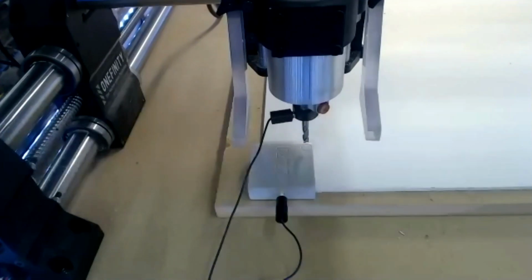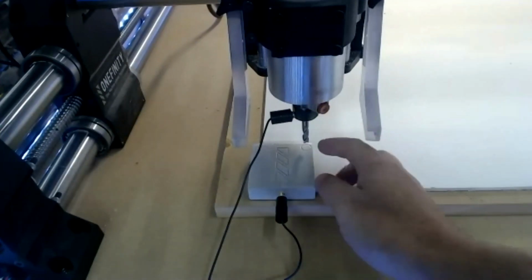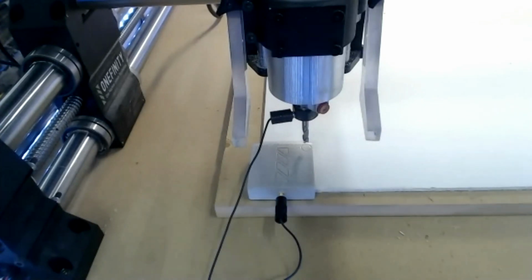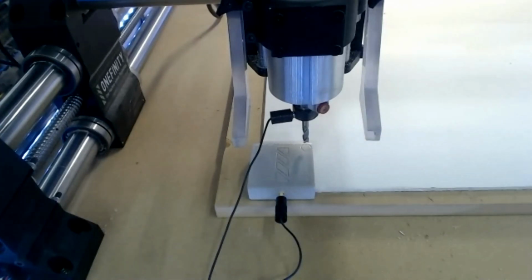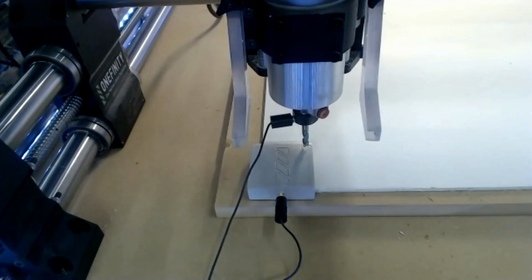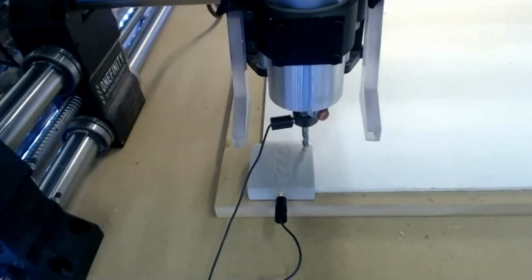Okay. So I have my proper probe tool information. Enter the diameter, that's how big this bit is. Make sure you have that set right or it's not going to calculate the math right. This is a 0.25 inch bit. So I'm going to hit set and it's going to move down and touch it. It's going to raise up and touch it even slower the second time to get a more exact one.